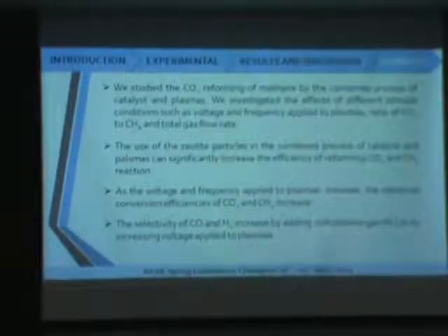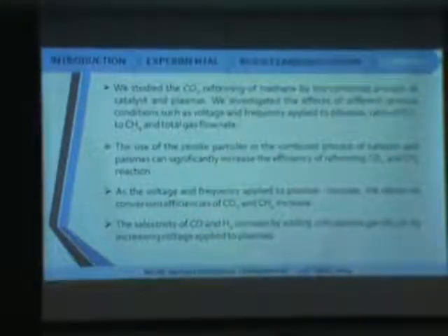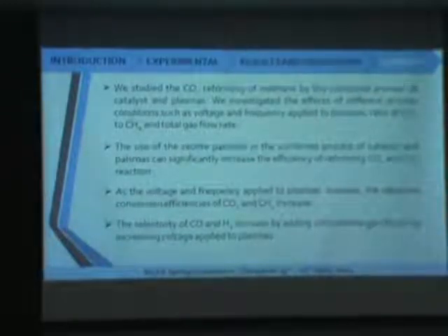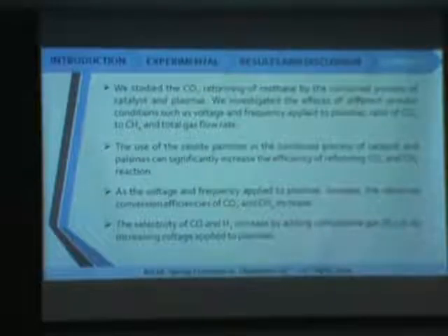So let me summarize our research. First, we studied the carbon dioxide reforming of methane by the combined process of catalyst and plasma, and we investigated the effects of different process conditions, such as the voltage and frequency applied to the plasma, the ratio of carbon dioxide and methane, and the total flow rate.